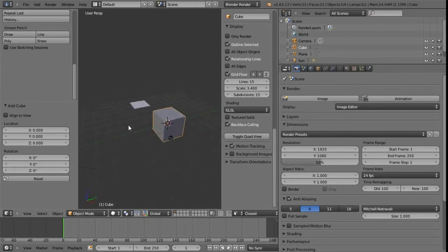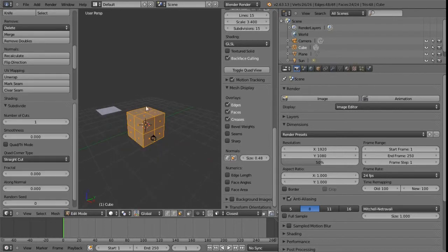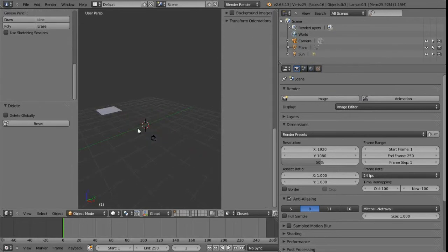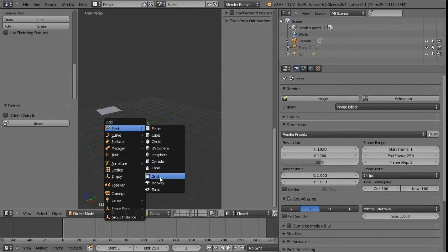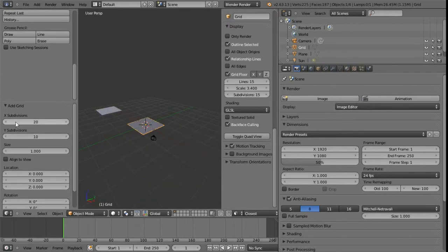In Maya, what you will usually get is the subdivision options. So you could maybe create the amount of geometry we want to contain within this cube. In Blender we don't really do that. We probably just take that as a separate option, an additional operation, of which then we can start to decide exactly what we want to use there. However, some of these tools, like for example the grid, is essentially the same as a plane, but we do get the option to preset exactly how much we want to be subdivided.